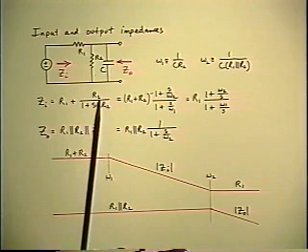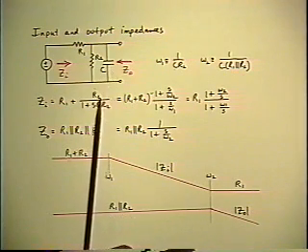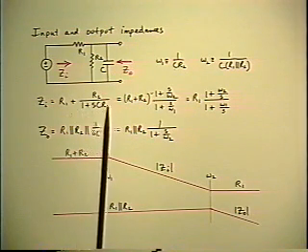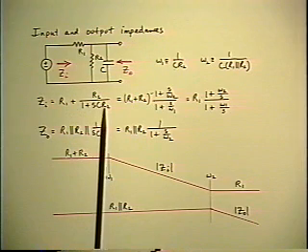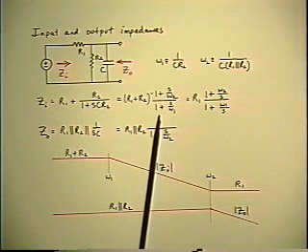Remember, we've already seen that a resistance and a capacitor in parallel has an impedance which is equal to the resistor with a single pole corresponding to the time constant of the C and the R. One line of algebra to cross multiply gives you the factored pole zero form.